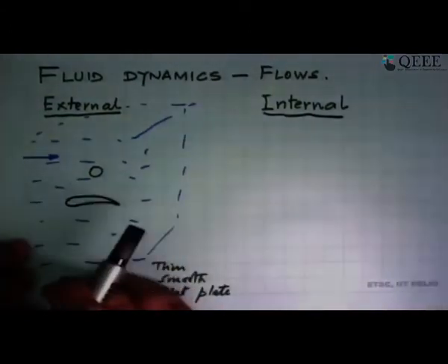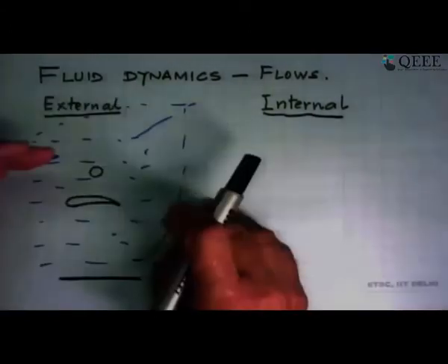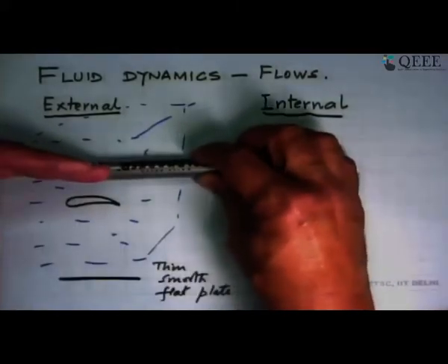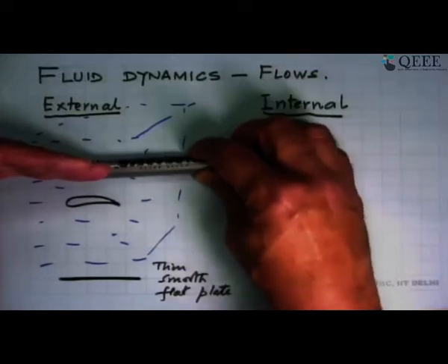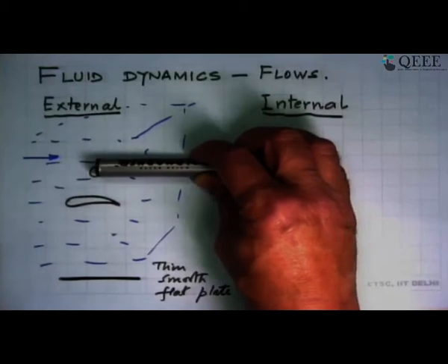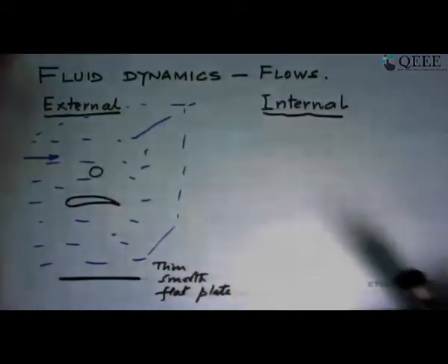And then we say, I will align it with the flow. So assuming that we made a very nice uniform flow, how do I make sure that the plate is exactly aligned like this? Well, in the real world, it will be off within, say, plus minus half a degree, 0.1 degree, 0.2 degree. It will not be 0 degree. But in theory, we take it as 0.